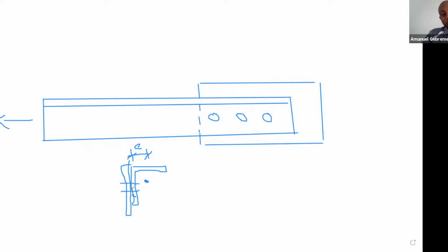What this does is it actually produces additional forces to tension in this member. So shear lag is in fact additional unanticipated forces that you would get in your angle from the way in which you're connecting it. This is typically unusual because whenever you take your software analysis program and you analyze members, it assumes that all the members are loaded through their centroid. That's why the structural analysis software is, in that sense, very dangerous. Because what it doesn't account for is the fact that the way you connect the member to something will induce some other forces. In this case, it could be bending. You could represent it in many different ways. We call it shear lag.